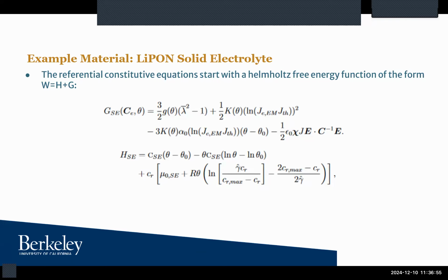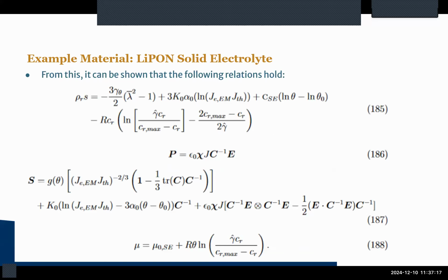And this is based on a thermoelastic neo-Hookean, adjusted to include electric effects in a way that does not make it piezoelectric, along with giving it the chemical potential that we expect from this material. And chemical potentials usually do not depend directly on the magnetic field, although you could always append terms in order to add some sort of dependence. And so following the whole Coleman-Noll argument, but not actually following it, you can eventually show that these are the case. And basically P is your polarization. You get a polarization that, this basically says that the material is a linear dielectric, which we expect.